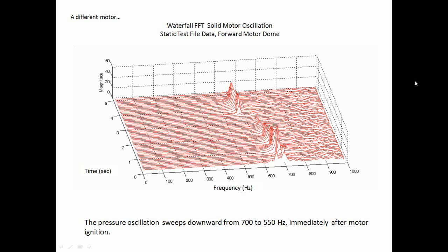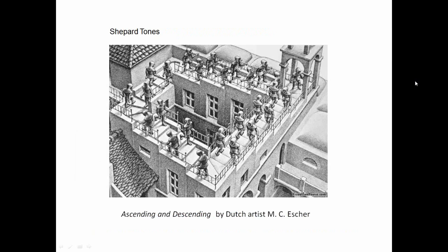But of course, we have to do some analysis to prove that, and we also need to do some testing to verify our isolator stiffness and make sure our isolators are linear, or see what happens if they're at hot temperatures or cold temperatures, or whether they bottom out. So designing and testing for isolators does require quite a bit of effort, but it's effort that pays a great dividend.